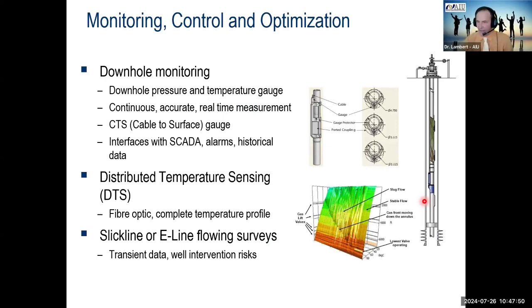Also, can we use liquid instead of methane? You cannot use liquid because, if I go back to the principle of gas lift, it is primarily based on the principle that once your gas is injected into your fluid, the density of that mixture will change. With all that gas being injected and mixed with the fluid, it will take the fluid to the surface. If you are just injecting fluid, you are not changing anything. You will not lift anything.